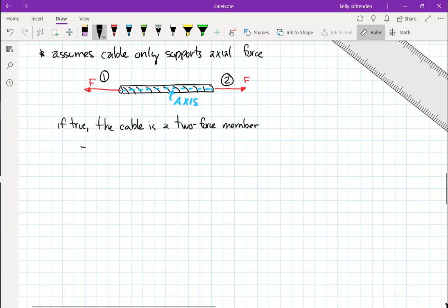It means that there are two equal and opposite collinear forces. Although that kind of is implied by the other, I'll spell it out. So in here I've got two F's, same magnitude, but in opposite directions. One's going left, one's going right. So it's always that way. There's two of the same magnitude and they're collinear, so they're on the same line, but they're pointing in opposite directions of one another, wherever the line is oriented.